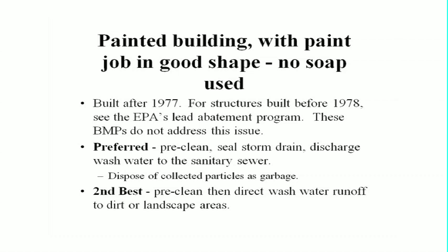Preferred method is pre-clean, seal the storm drains, and discharge the wastewater to the sanitary sewer, which is always going to be your first choice. Dispose of the collected particles as garbage. Second choice, pre-clean and direct the wastewater runoff to a dirt or landscaped area.